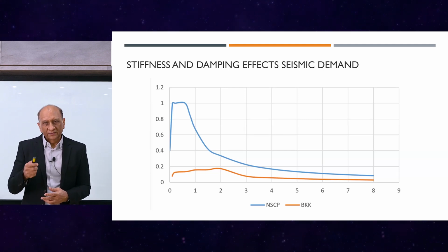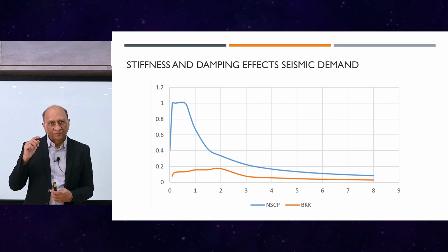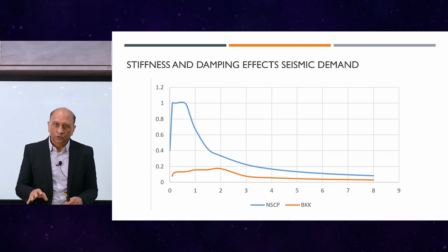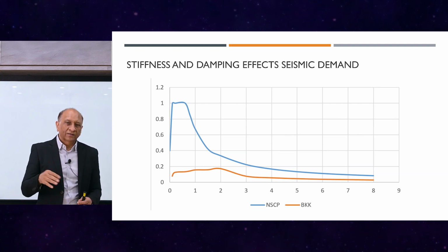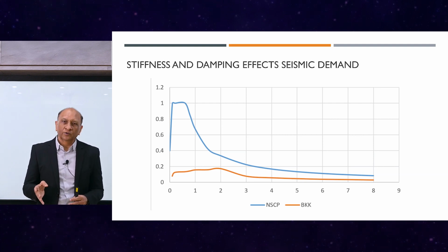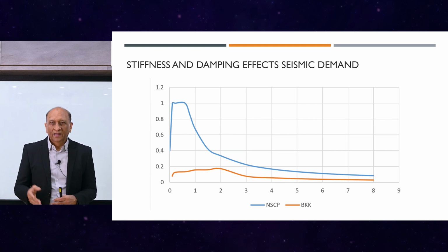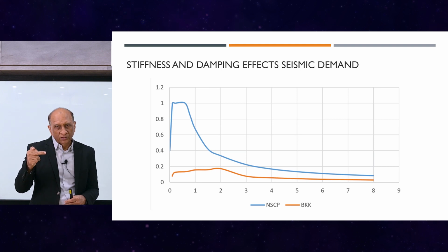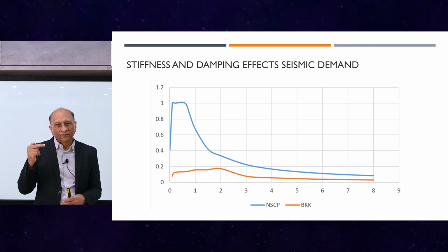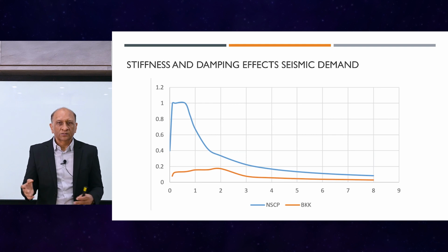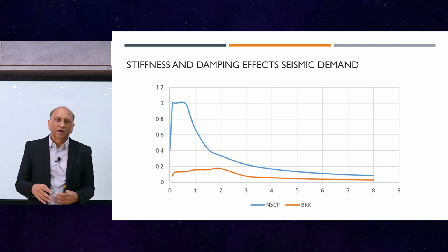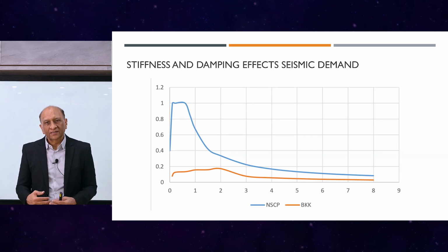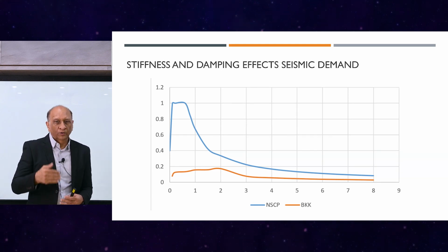So coming back to that figure, you can see here that R is the reduction from the design basis earthquake down to the design level. This value is used for design of ordinary members like beams and columns, which are not critical, especially for bending and ductile behavior. We magnify that demand by omega naught to reach the expected true demand for critical members like collectors of a diaphragm, shear walls, and others like transfer girders, which are very critical for the safety of the buildings. We will have omega naught.